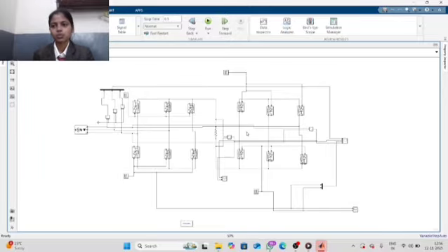Each phase provides a sinusoidal voltage shifted by 120 degrees. Then the SCR acts as a control switch. The control circuit triggers them in a particular order so that the load receives a portion of the 3-phase voltage. Depending on which SCR conducts, the load sees either positive or negative voltage.